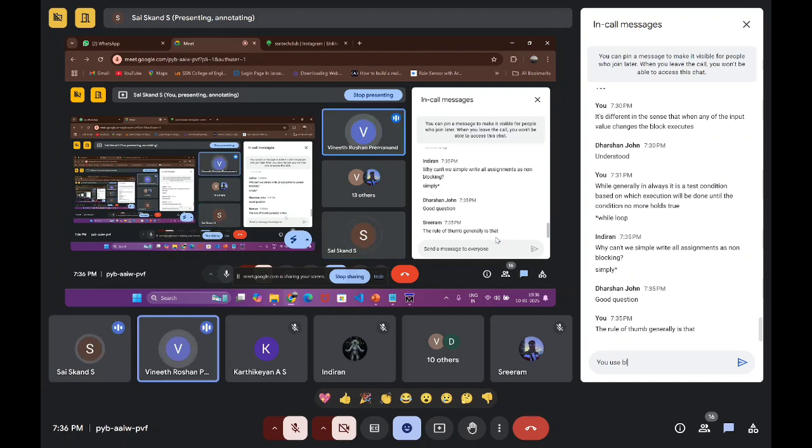Like for a simple example, you guys know the if statement, right? If some condition, then do something, else something else. At a lower abstraction level, there are branch instructions, which we kind of covered. We mentioned that some commands are branch if equal, branch if not equal. Now we compared two numbers. If they are equal, then the subtraction of them should be zero, right? So that's where that zero flag is used.